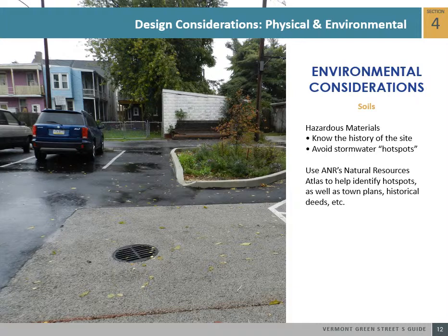So hotspots include areas where there is a potential risk for spills, leaks, or discharges, such as petroleum distribution centers, hazardous material loading and storage facilities, and many other industrial sites. Due to the threat of pollution migration and to prevent groundwater contamination, stormwater that encounters hotspots should not be treated with stormwater infiltration practices.